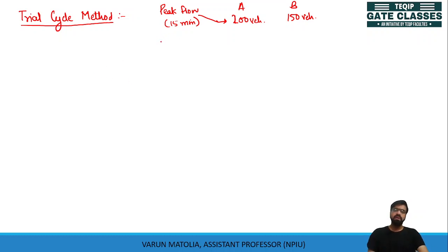We have amber time, which is already conveyed, that we have amber time of 3 seconds here, 2 seconds here. This is designed from the previous calculation which we have done during the clearance interval, based on your width of road, based on your braking and reaction time. So this is your amber duration. Then we are provided with your headway. This is your time headway.